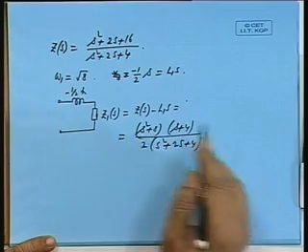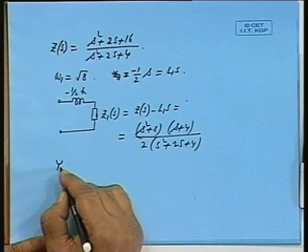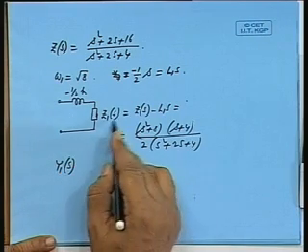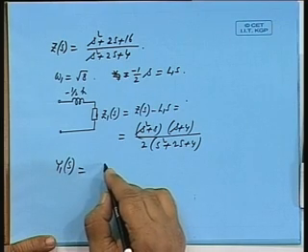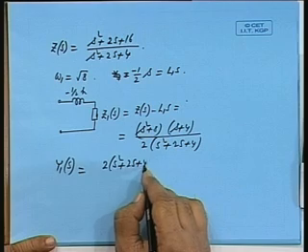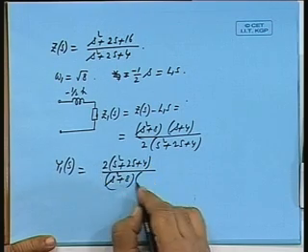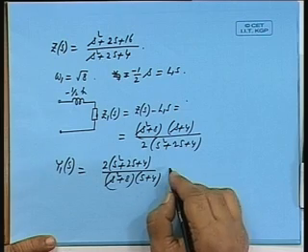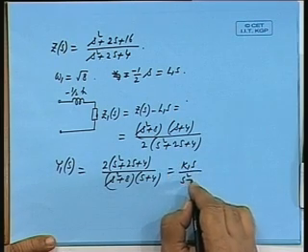we know we can make partial fractions. So, this 0 is to be converted to a pole. So, we can very easily realize Z1s in terms of an admittance function, which will be 2 into s squared plus 2s plus 4 divided by s squared plus 8 into s plus 4. We write it as k1s by s square plus 8.